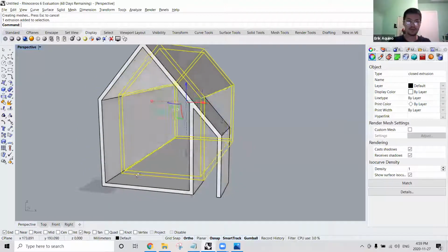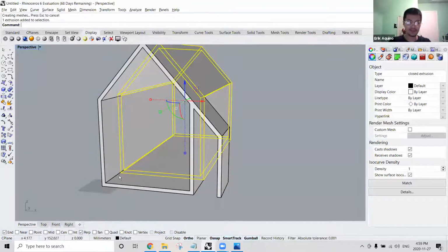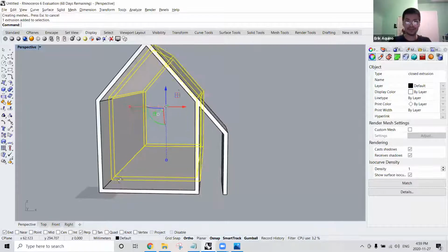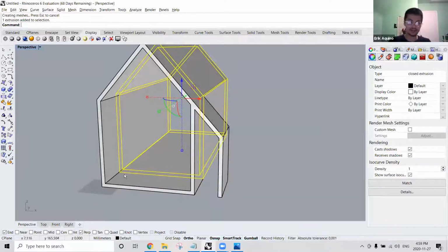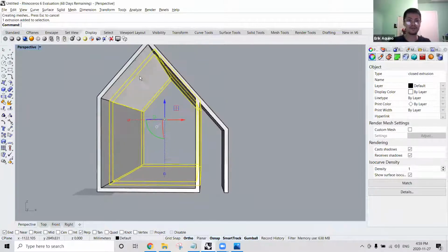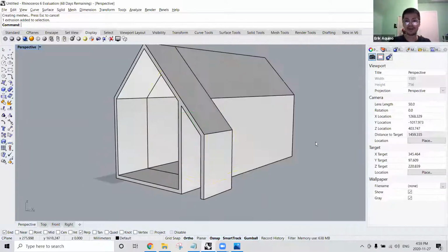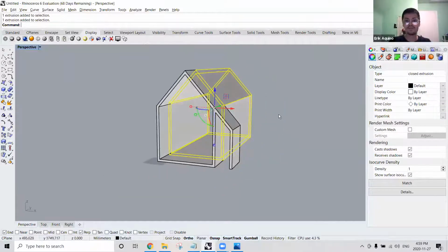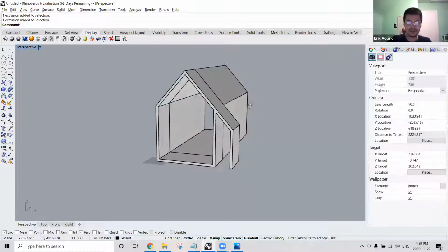So when you're thinking about creating your profiles or making your shapes, you'll want to have a unique profile and an object for each building element. So in this case, I would, for my actual project, make a floor profile, make a wall profile, and a roof, which are separate from each other. That way you have more flexibility in modifying these elements, but that's how it would be constructed in real life anyway.